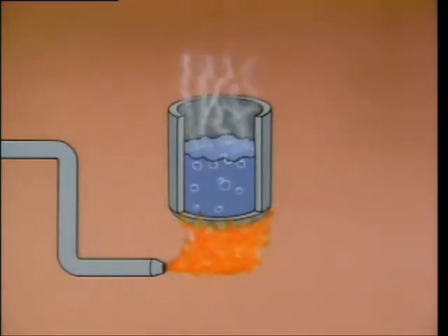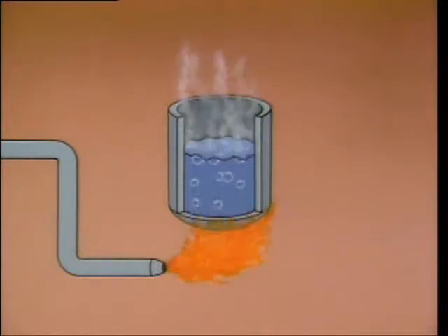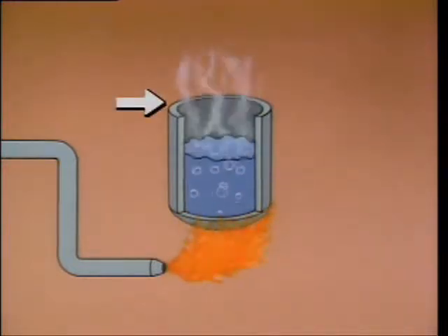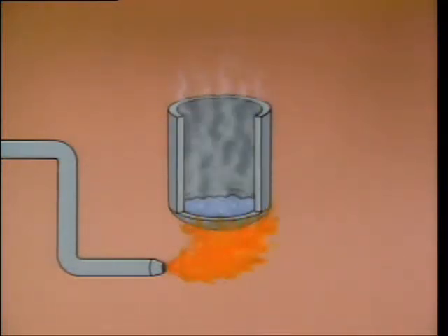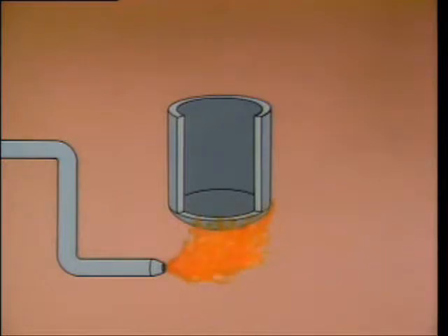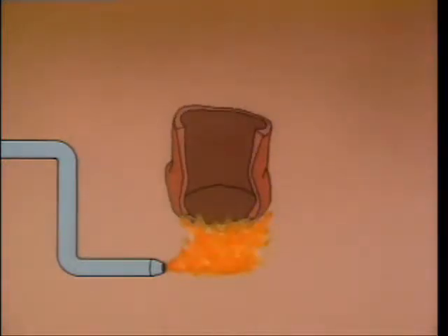But a boiler modeled on this example won't work for industrial applications. First of all, the shell is open to the atmosphere, so there's no way to collect the steam. In addition, as the water boils to steam, there's no way to replenish it. Without water, the shell could overheat and be damaged. Given these factors, we'll have to make some changes.